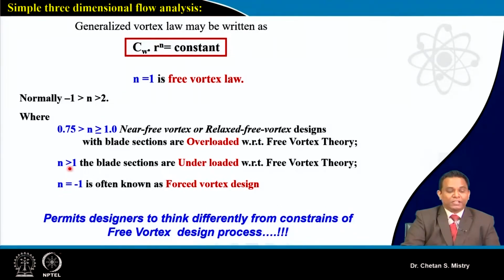Now if we consider n greater than 1, that gives an underloaded design with respect to free vortex design. And if I take n equal to -1, that is defined as a forced vortex design.